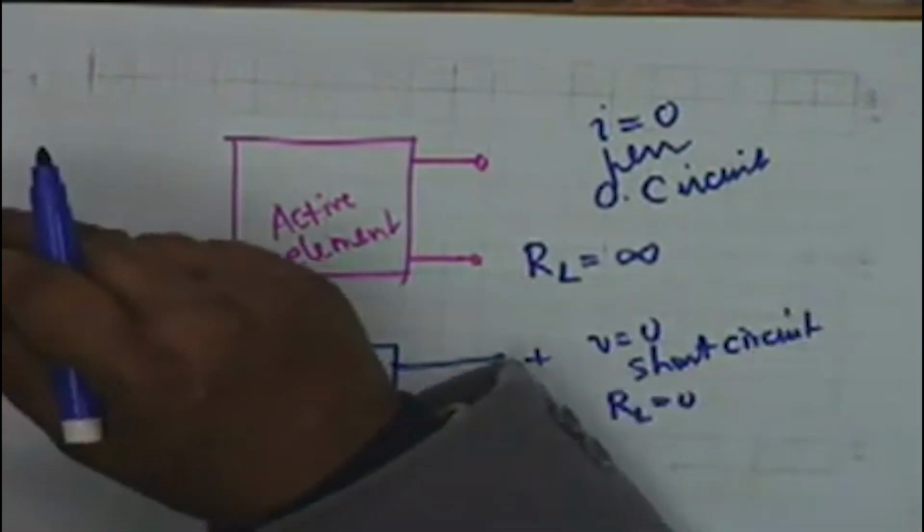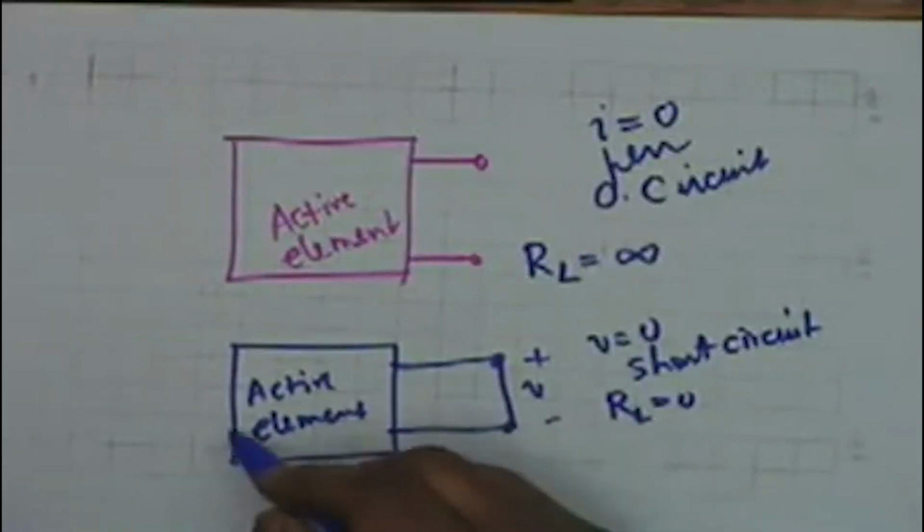Short circuit is usually accompanied by a spark because of the large amount of current that can flow, virtually zero resistance. And if this active element is an ideal voltage source, then how much current can flow? Infinite amount of current, which also points out the fallacy of conceptualizing an ideal voltage source. An ideal voltage source naturally cannot exist. If it can exist, then it should be capable of delivering infinite amount of power, which is not possible. Agreed?